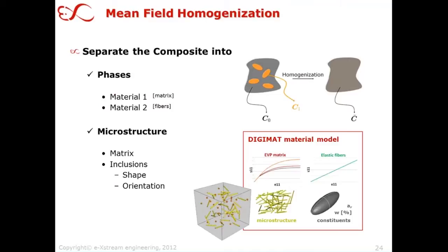So basically two different material models, and what we do is that we use then nonlinear material models to describe the polymer matrix, and you will see later on what kind of possibilities we offer here. The glass fibers themselves, they are quite simple. So here basically we take some linear elastic isotropic material properties which we associate to the glass fibers.